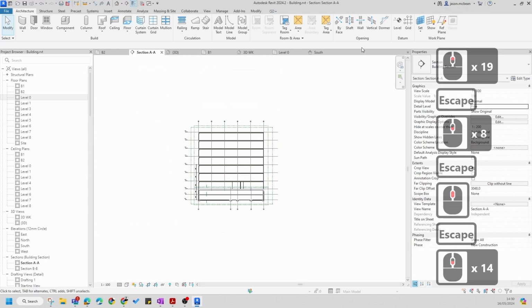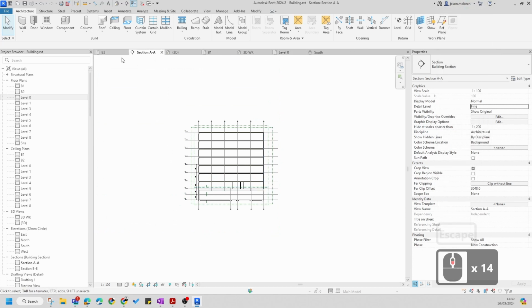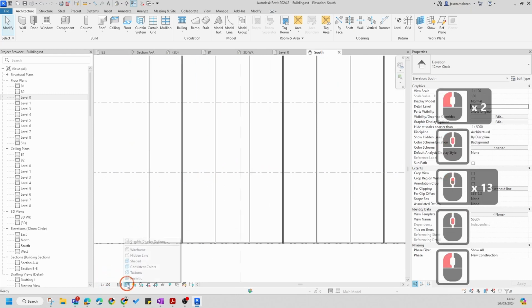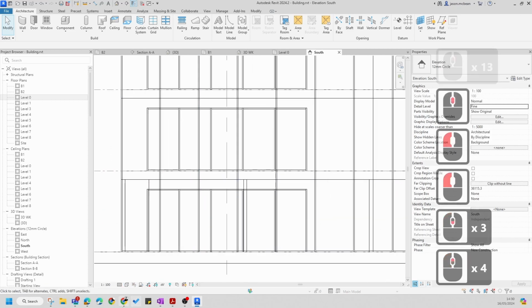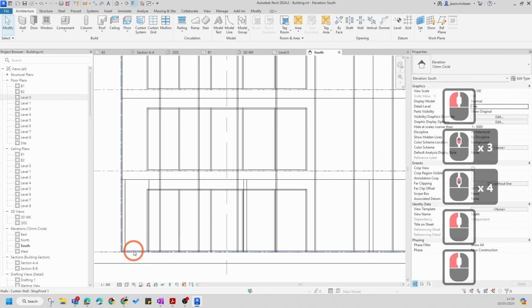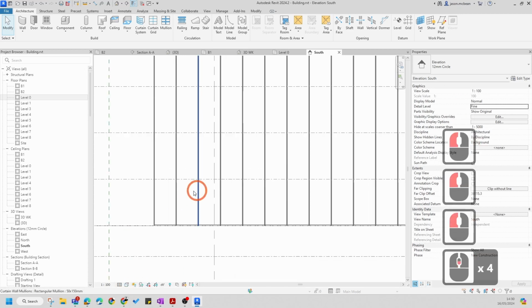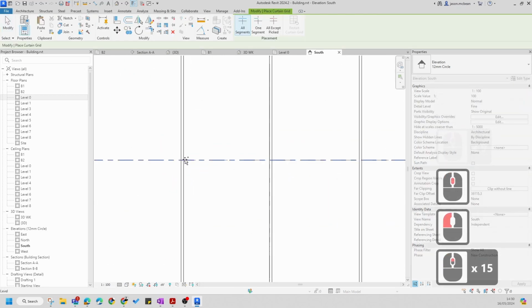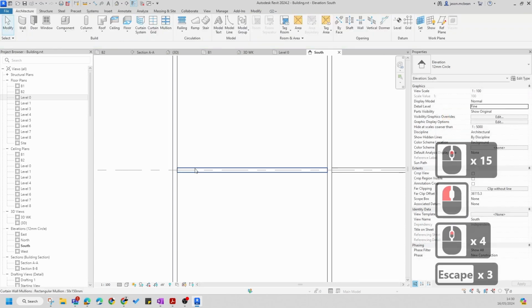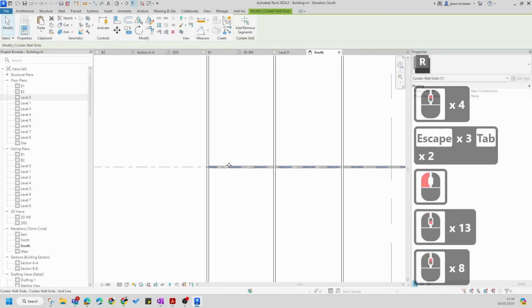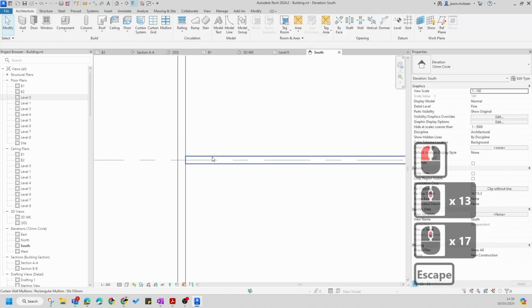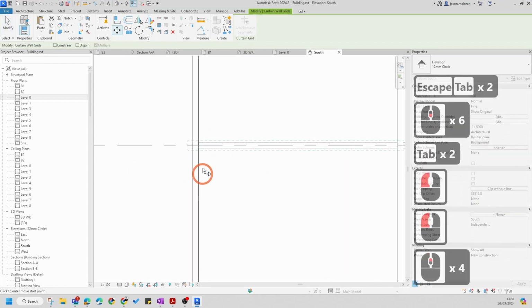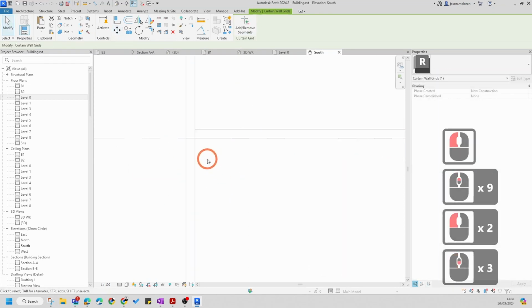Now, if we go to elevation view, I'll show hidden, because I want to see the floor slabs in the background. I know the levels, so I kind of know what I need to do. What this allows me to do is introduce grids now. So I'm going to drop a grid in there, and it creates a whole new mullion system to work with this floor. When you tab this mullion, once or twice, it'll allow you to select the center line of that mullion, and I'm going to move this down because typically this will start on top of the slab.